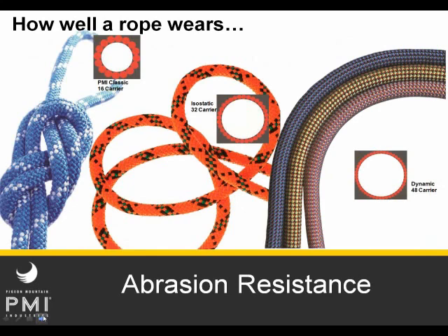One clue that you can use to determine abrasion resistance has to do with the number of bundles of yarn that a rope sheath has. Remember that rope making machine that we saw earlier on the slide? We didn't actually talk about it a whole lot, but the number of yarn bundles that are used in the weaving of that sheath is actually an important factor in abrasion resistance. Sometimes you hear this called carriers. A 16 carrier rope uses 16 bundles of rope to go around the core.